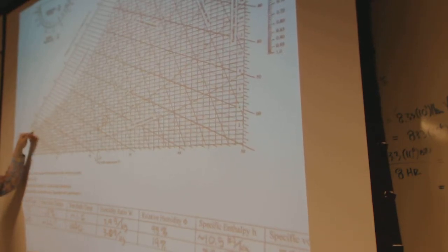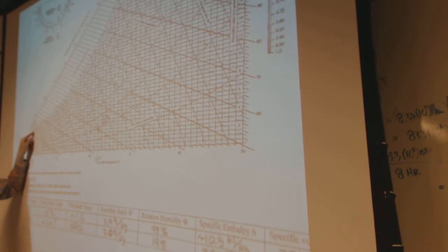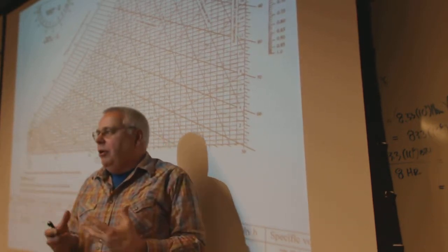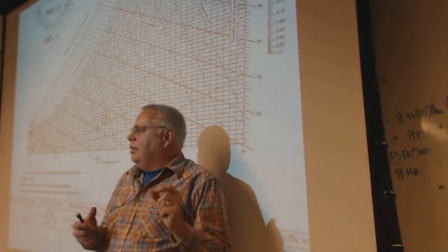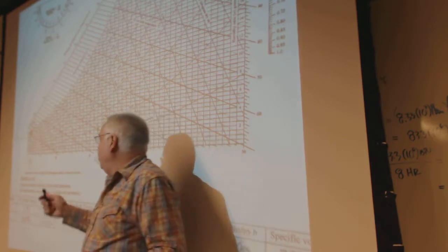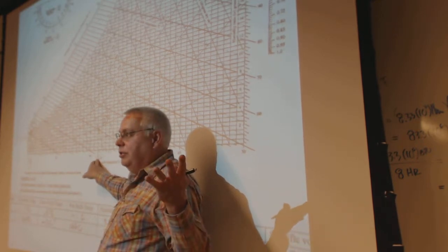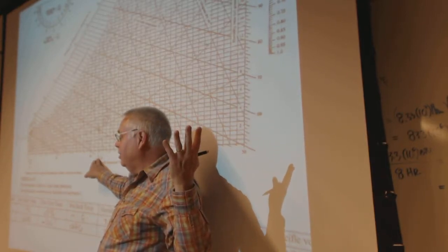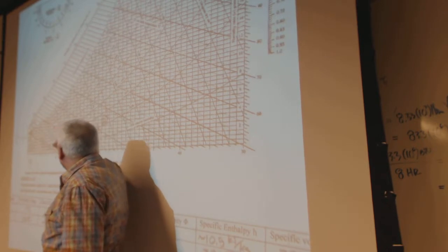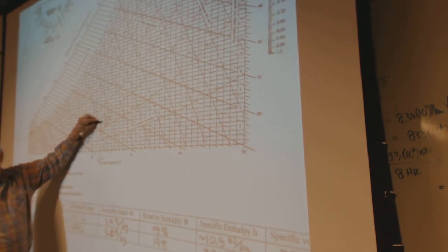If all the outside air came in here and they just heated it up right now, it would have this same amount of moisture in it. Right now it's 95% relative humidity outside, which says the vapor pressure of the actual number of water molecules, the partial pressure of it, is 95% of the saturation pressure at 1 degree C, which is cold. It's going to be really low saturation pressure. When you heat it up, the saturation pressure at 22 degrees C is a lot higher because it's a hotter temperature. If it got all the way up to 100 degrees C, then the vapor pressure would be 1 atmosphere, 101 kilopascal. But the pressure didn't change, same number of molecules. If they just took that outside air and brought it in, we would have a whopping like 24% relative humidity.